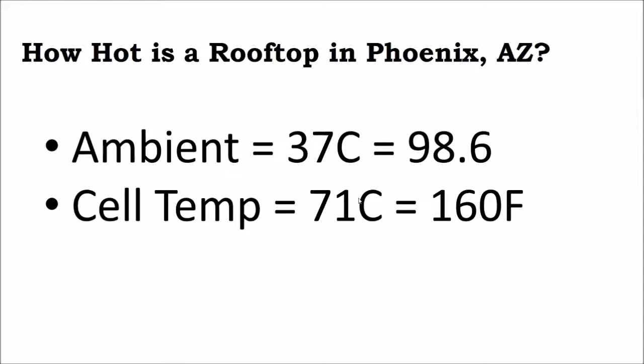And commonly, the wiring that's rated for inside your home only has that 75C rating, or maybe even less. And so it's very possible for wires on a solar array or on your rooftop to get to a temperature beyond 75C. So if they don't have that 90C rating, they could start burning up on the rooftop.